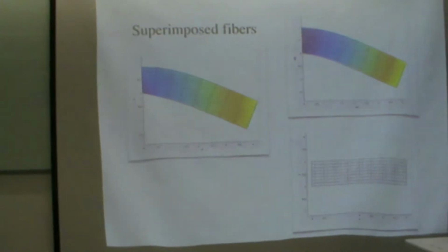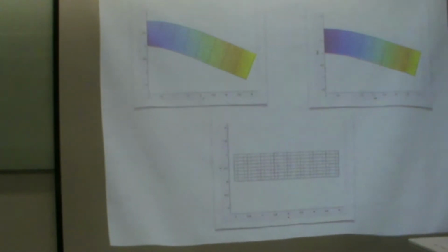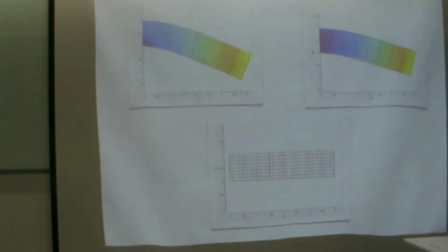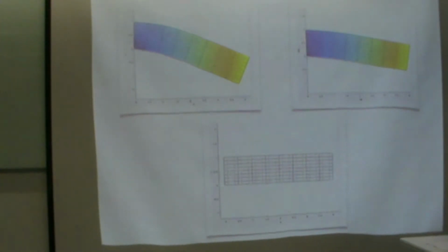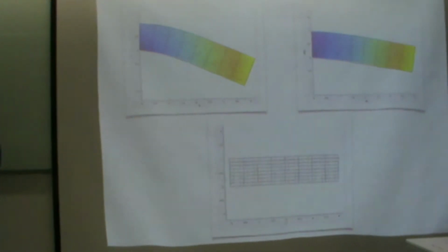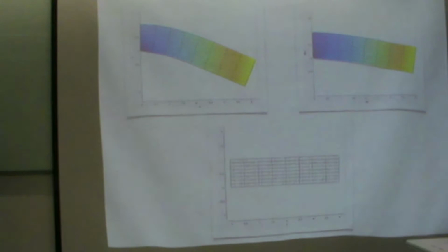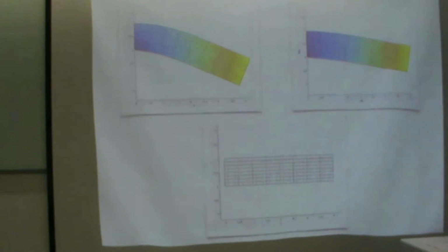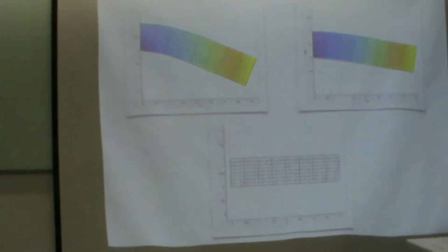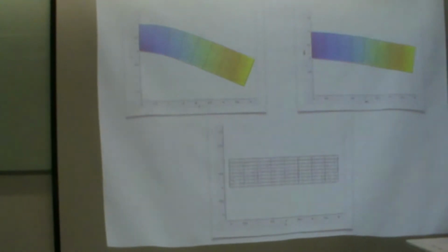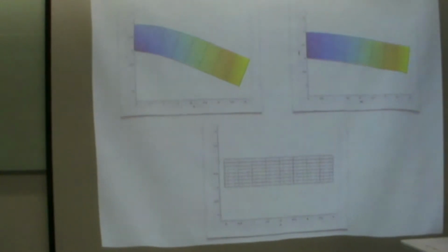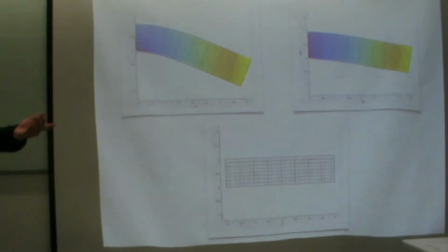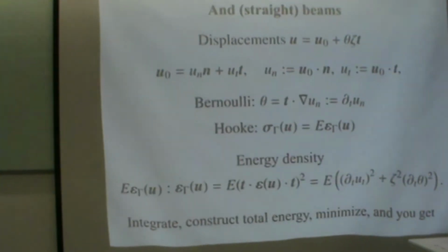fibers. If I rotate the fibers slightly, this is a 45 degree rotation of the fibers, you see you have a stiffening effect. If I make the fibers horizontal, you have a stronger stiffening effect. Okay. So maybe this is not so much of an improvement to the anisotropic material models that they actually use, because what they do is that they superimpose an elastic model which is a continuum model. I do it discretely here, so I don't know, it's just an option.